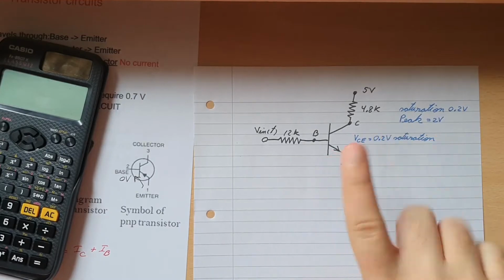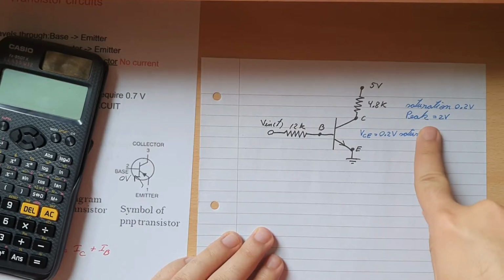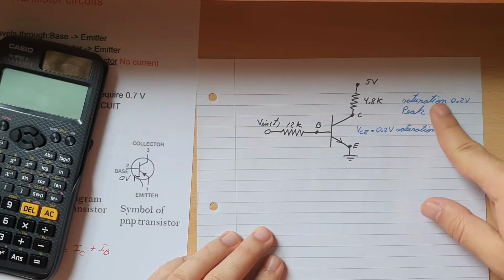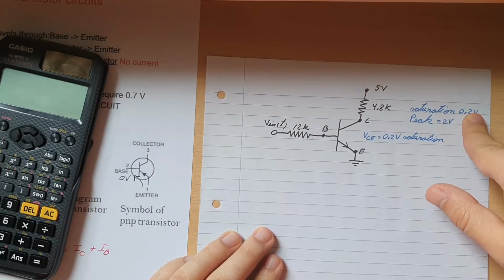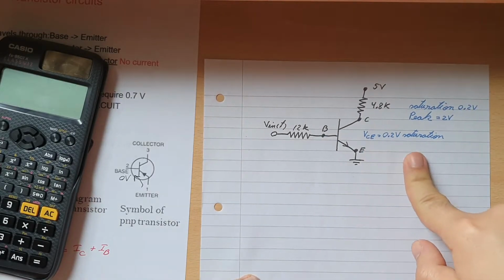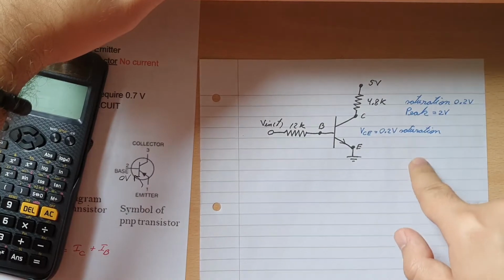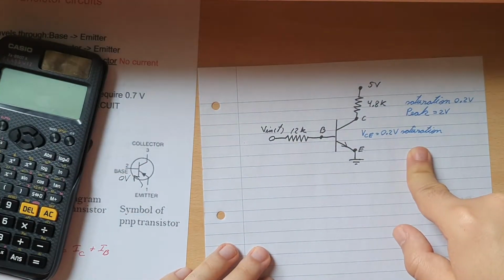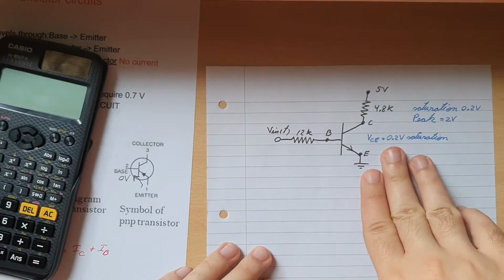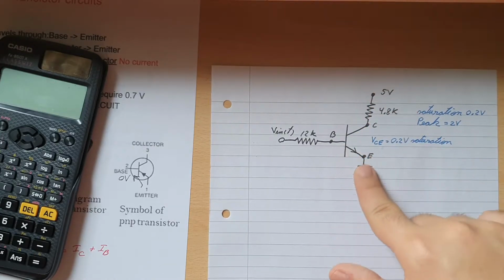Why is that? Well, there is no resistance at the emitter in the first place, but what you notice is that the voltage in is actually a peak voltage, which means it's an AC source of 2 volts, and this new word called saturation of 0.2 volts, it's inside VCE, and this saturation just means that the VCE will be a bit lower, let's say. Okay, I mean, it doesn't really make that much of a difference. It only makes a difference when you calculate the voltage going through it, and you'll see in a second what I mean.